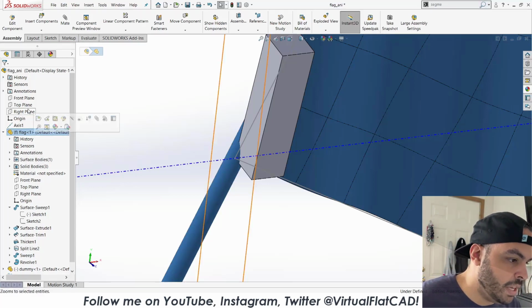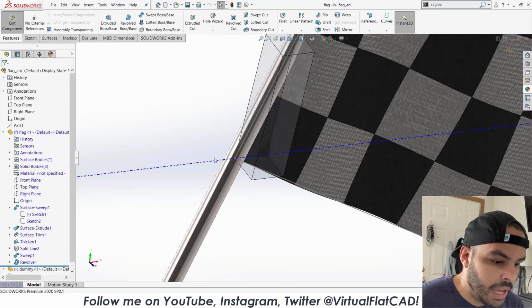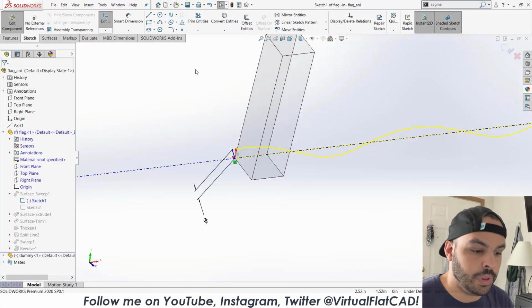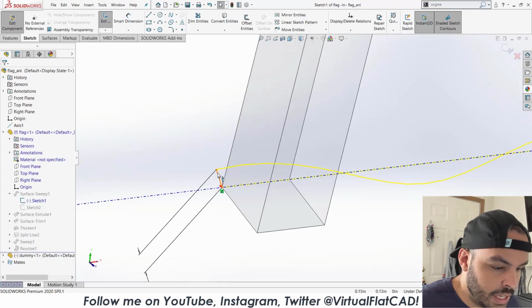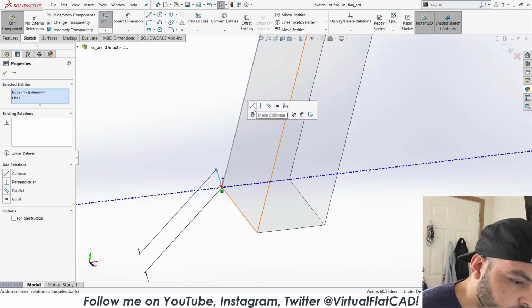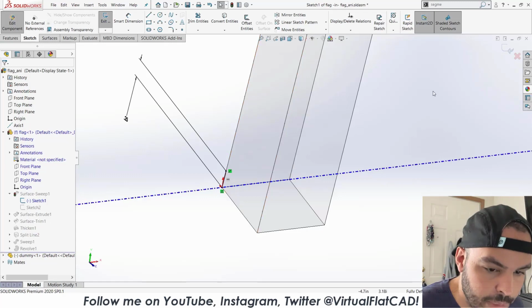The advantage of that, you're about to see: if I get flag, edit component, I can edit this sketch and actually see the other components in the assembly, and I can actually put relations to that, which I think is very handy. So all I gotta do is get this line and make it collinear to that. And that basically links them up.